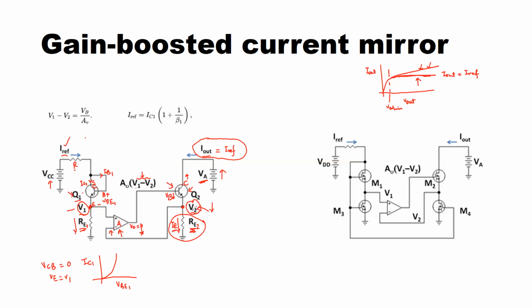And therefore, whatever the proportion by which V2 increased initially, due to the operational amplifier's negative feedback that we are taking from here at node V2 and the operational amplifier's very high open loop gain, we make sure that we bring that voltage back to its original value. That is, V2 comes back to its original value.